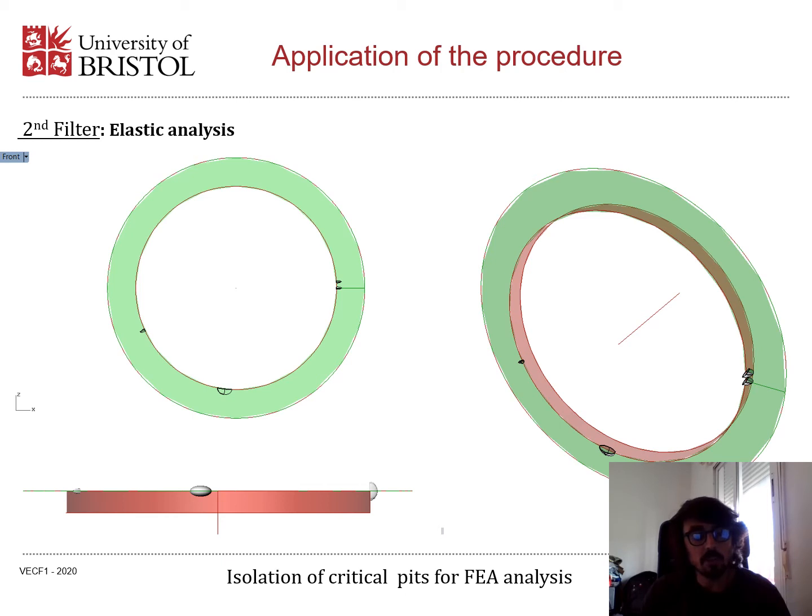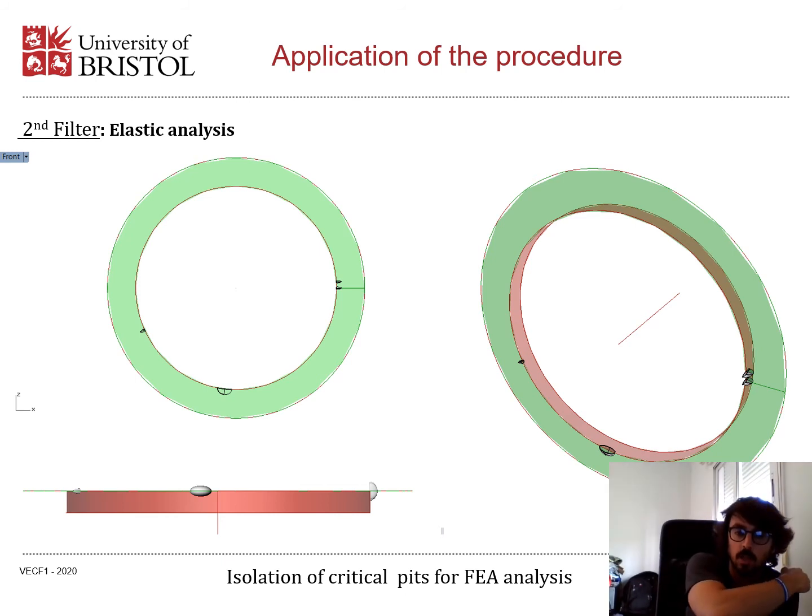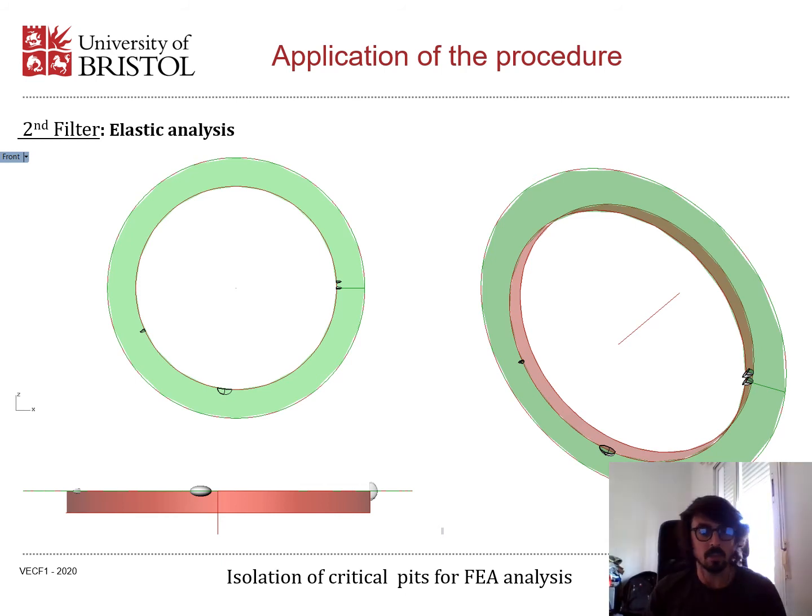We used the rendering tool to create STL files and to input those files into FEA analysis software, to create FEA meshes and perform the elastic FEA and obtain the stress fields ahead of the different notch tips.